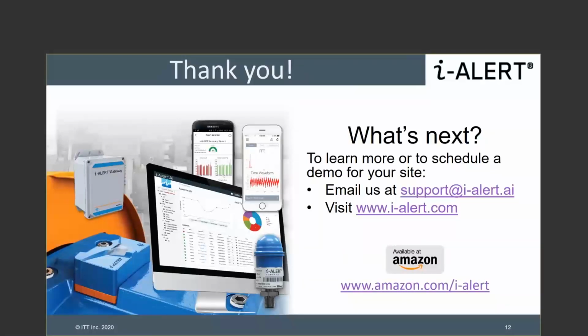As a newly developing condition monitoring program, you've got a blank sheet of paper and you're trying to set up a condition monitoring program. I would say the first thing you would do is look at all the assets you have in your plant and categorize those as to which assets are critical. By critical I mean vital to the operation of the plant. And then I would create tiers of these. The second area might be the pieces of equipment that you have problems with from time to time, but are not critical to the operation. So-called bad actors, machines that don't necessarily have a redundant backup and can cause issues.